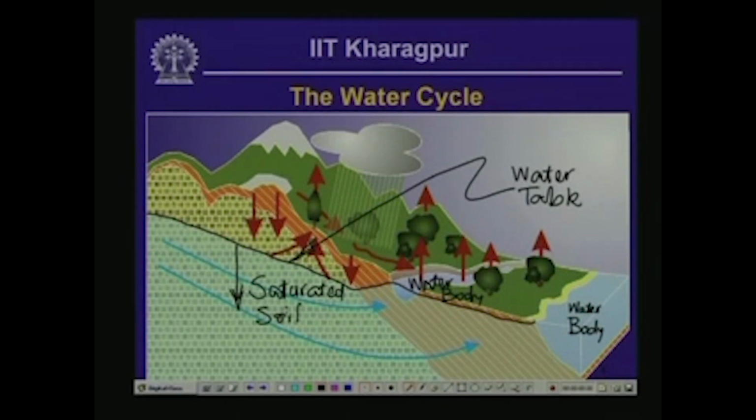and most of the groundwater that flows from one location to another, we'll look at it in detail later on, but I just wanted to introduce the concept here. Most of the groundwater flow takes place through the zone of saturation, and above the water table is the so-called vadose zone, that is a layer of unsaturated soil.